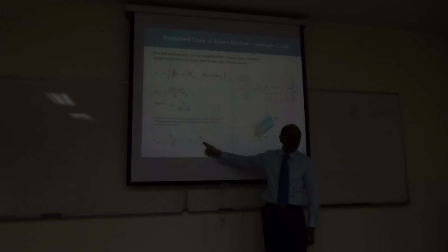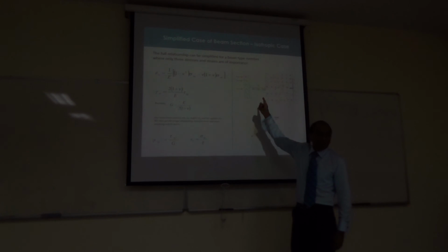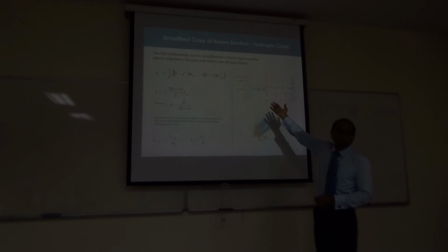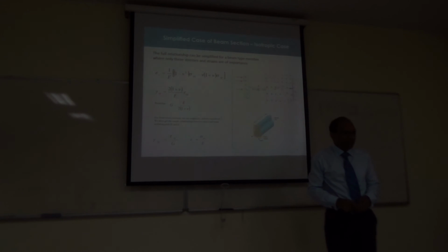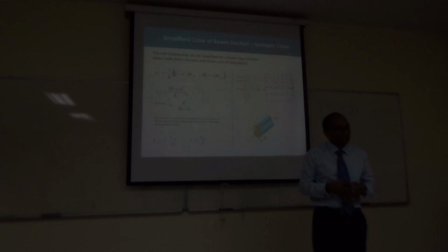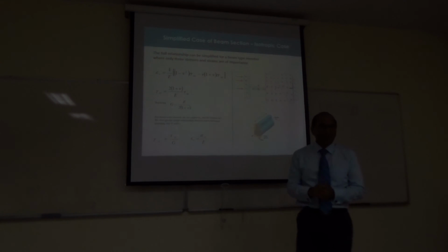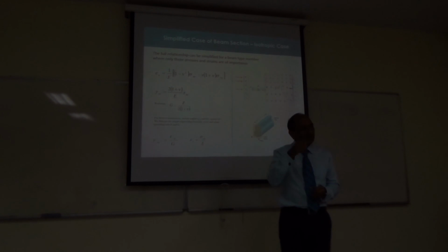So basically this relationship, stress over strain, is a simplification of the big matrix, right? This is only a special case of the full 6 by 6 matrix relationship between stress and strain, by putting certain things to be 0, right? Because we are simplifying it for a certain loading case. So the point being that this same big matrix contains all of the behavior, and we can simplify it for a particular application by setting the values appropriately to 0, depending upon what we are doing.